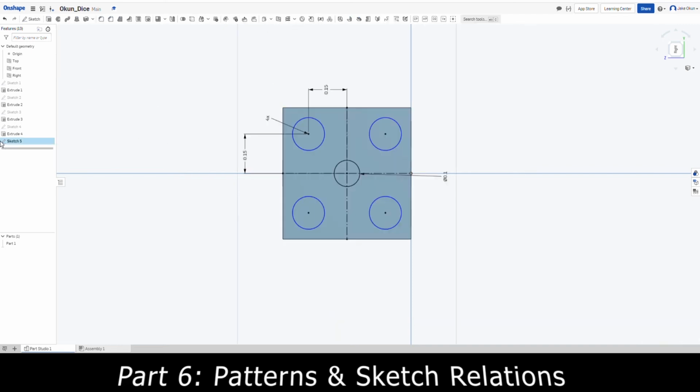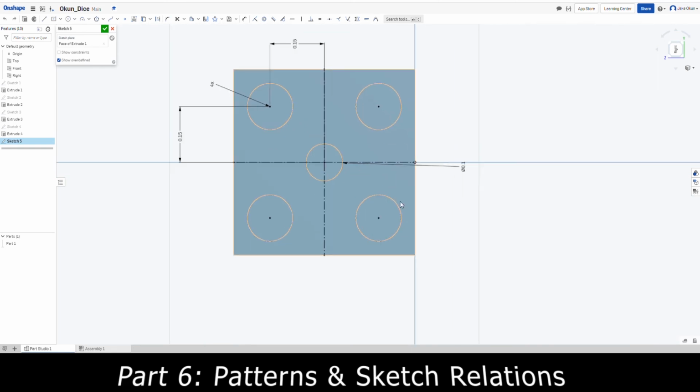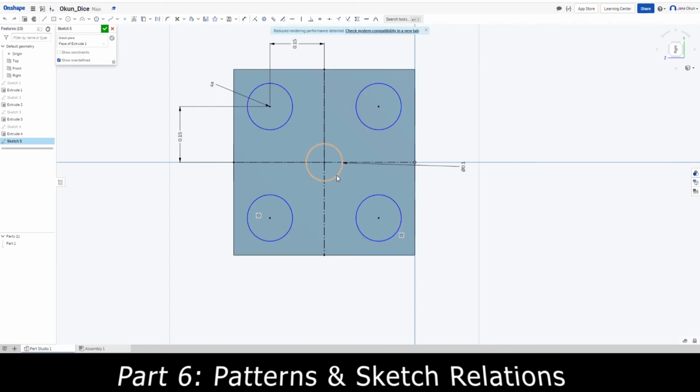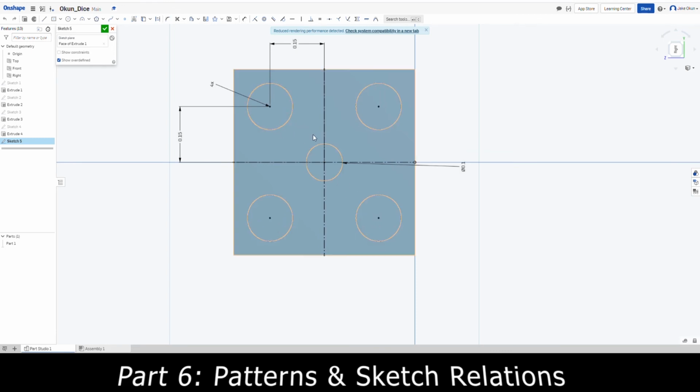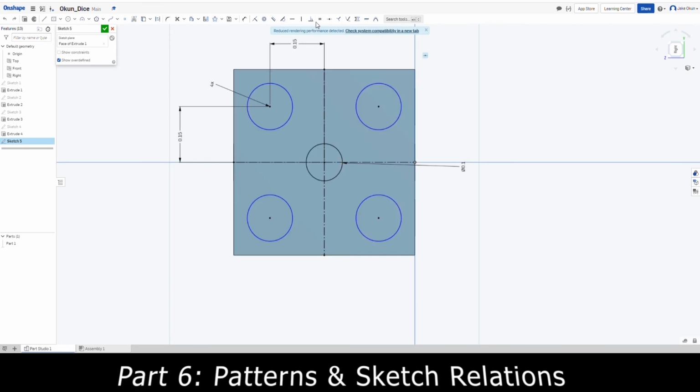And then I'm just going to go back to the sketch, double click on it, and then just to make sure everything looks right, because it does, I can just tell by looking at it, we should be good to go. The only thing that I'm going to do is you'll notice how this is the correct dimension, but these aren't. Now to fix this, it's a very simple fix. So to do that, we're going to use a different type of tool. This one's going to be a part of the sketch dimensions tool. So we're going to use the equal tool.